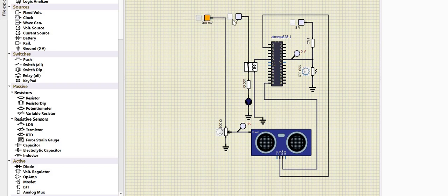So let's turn on all the power sources. When I start here, let's power the circuit. You can see the initial condition, the relay is not energized. Why? Because this is within 150 centimeter here. You see what is exactly 150 centimeter here, it resembles, and the lux is enough daylight, it is 999 lux, so it's enough daylight.